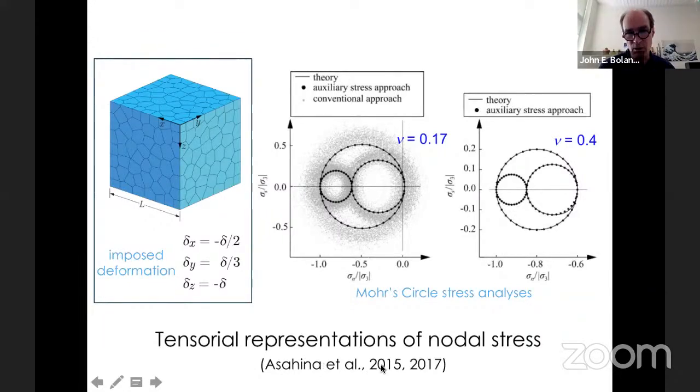And so through his work, and these are 2 publications that he led on, we're now able to model Poisson's ratio for the complete thermodynamically admissible range from negative values all the way up to 0.5 without any trouble. Conventional approaches, which I'll come back to in a moment, produce this sort of noise, meaning you're getting approximately proper stress values, but there's a lot of variation from theory.